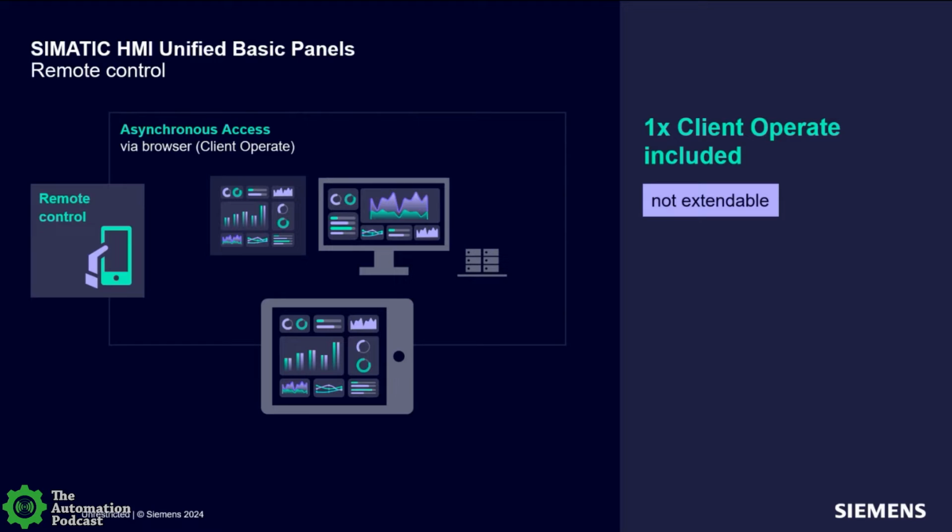This is saying really that our panels are not only just a localized service from the panel itself, but it also is a web server. So if you can get on the network of that device, and you've got users defined in that project, with your other device being a PC, a tablet, cell phone, maintenance personnel, or whatever, they can use these other mechanisms and not need to install any Siemens software on it. You're getting an asynchronous access, which means that operator is going to see their own set of screens and interact with the system in parallel to the localized operation.